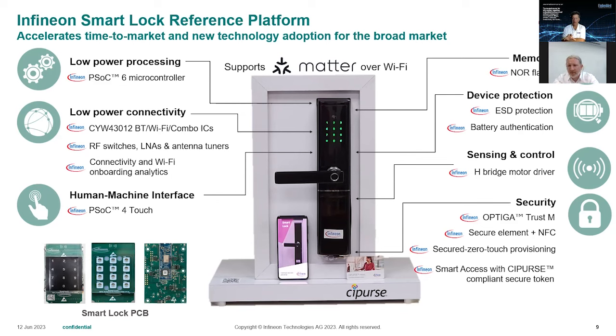Is this the actual reference platform that somebody would get from Infineon? Yeah, what I'm showing here as the miniature lock is an actual demo version, but here on the bottom left is the actual reference platform. So it's basically these three PCBs that are shown here that are physically inside of this lock. And the beauty with the reference platform is, hey, we understand everybody may have their own lock, they may have their own motor, they may have their own half bridge, so we make it easy for you to basically swap in and out